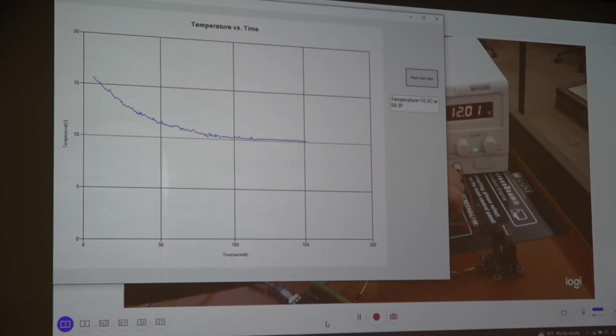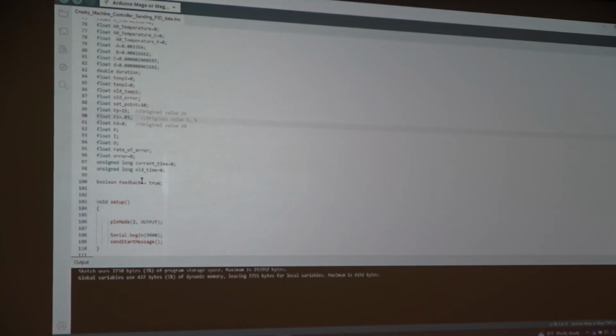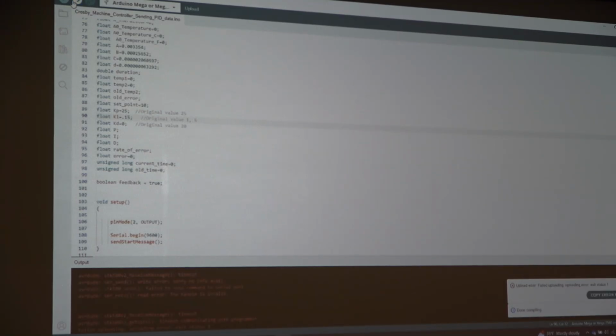Okay, let's do it again. Take the power off and let the block warm up a little bit. Let's get a little more heavy-handed with bumping that throttle forward and bringing up a bunch of throttle so that we rush headlong into our set point. Intend to overshoot. Ring like all day long.